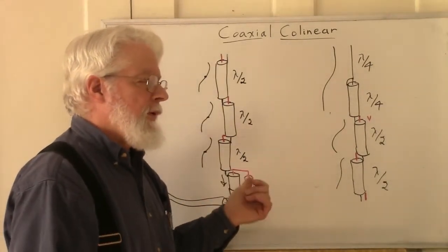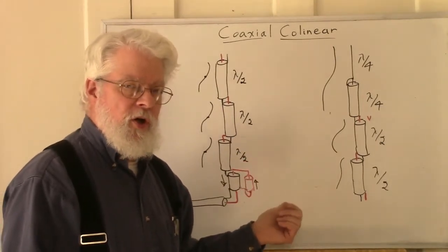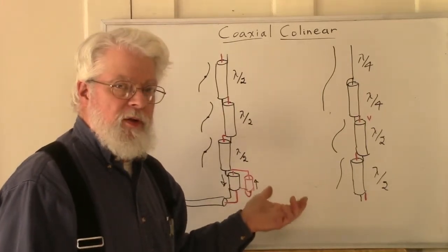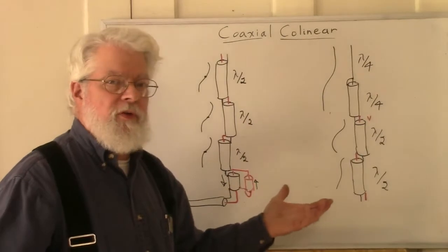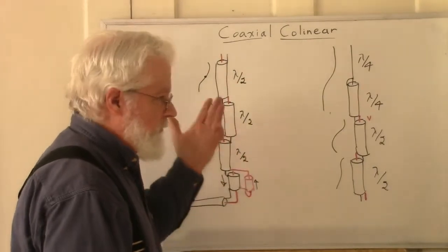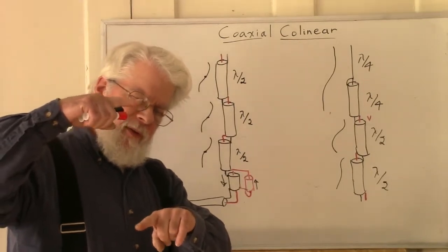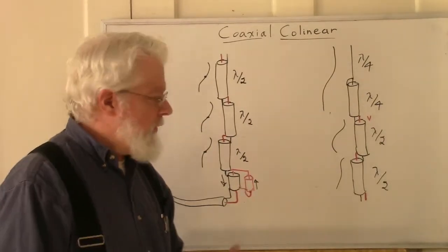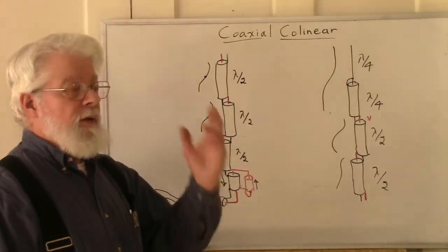I needed a UHF repeater antenna in a hurry. We set up a temporary repeater site, and I said, let's build a coaxial collinear. We needed a big antenna. We needed something with some gain. We wanted a decent antenna. Well, what does every ham have in his shack? Coax. So I basically took a bunch of coax and cut it up into little sections. I think they were roughly about 7 inches long, and soldered them all together in this configuration, stuffed them inside a piece of PVC with a cap on the top, and up in the air it went.